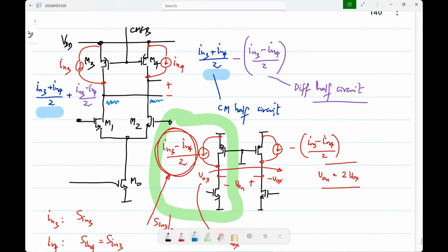The idea is the common mode rejection of the following stage will get rid of it. The entire idea behind differential circuits is you have common mode rejection somewhere. But if you have nonlinearity or something else, or if the following stage doesn't have common mode rejection, the common mode noise here also will have some effect on the circuit. But we are thinking of this whole chain of differential stages where finally you are sensitive only to the difference. If that is true, then any common mode noise will not have any effect.